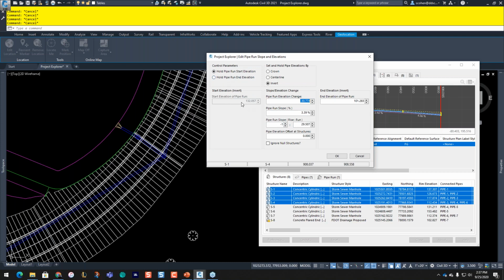This is my beginning. I noticed a little bit of not a bug, but just one thing you want to make sure you do: set your start elevation to at least something that makes sense, all right? Whatever the minimum pipe cover you need. Again, the rules should work for you, but you want to check that, make sure it works that way, because everything you do here is usually based upon the beginning, all right?